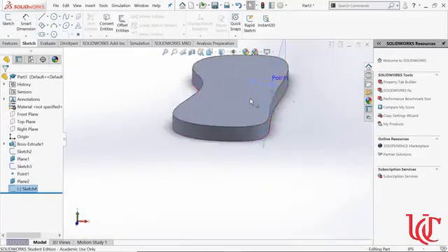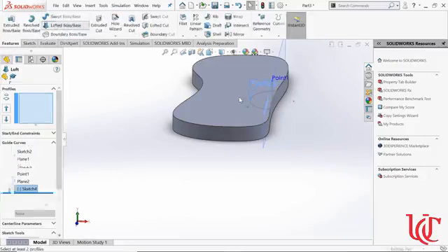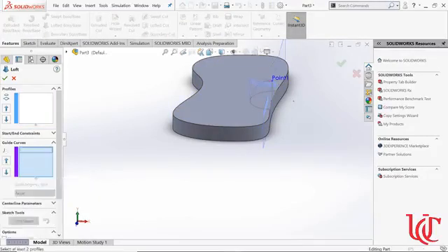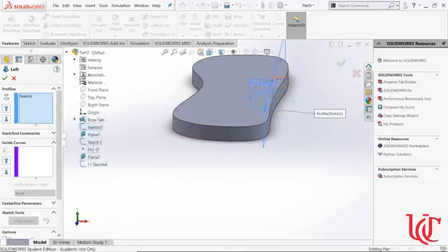That is going to be used as one of my guide curves. So now I'm going to specify when I make this loft that this curve and this line, which I made as well to go straight up, are going to define how my shape lofts from one sketch to the other, or from one sketch to a point in this case. So I go to features and say loft. Now, it already guesses that was a guide curve, but I'm going to pretend that wasn't there and just delete it. I need to select my profiles for my sketches first. So I'm going from what profile to another. Sketch 2 to, oops, let's try selecting my point itself. Sketch 2 to my point.